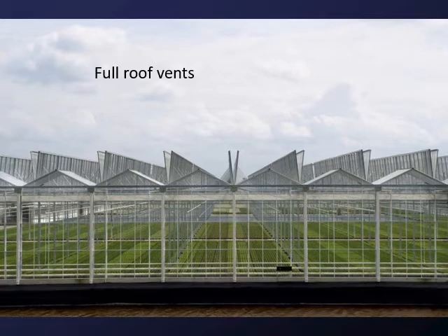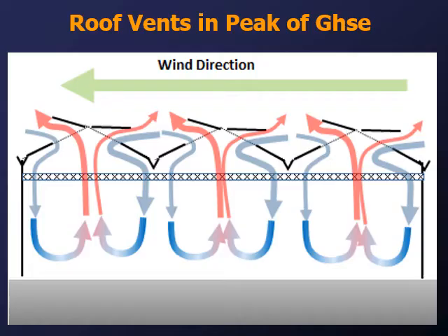And by the way, you don't have to open them that extremely. If there's ice, ice doesn't move. You can't compress it. The second you move these even an inch, it smashes all the glass. And we're not talking a few vents, we're talking the entire roof. So that would be a colossal error from an operator or a grower's perspective.